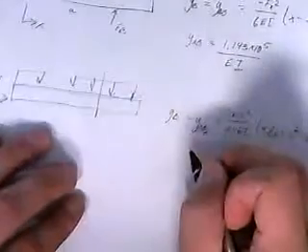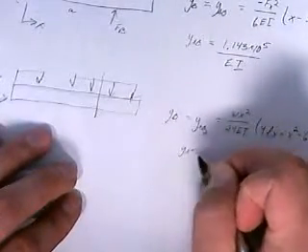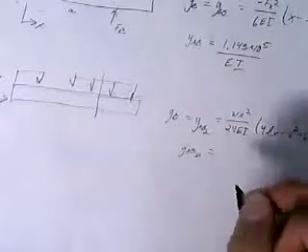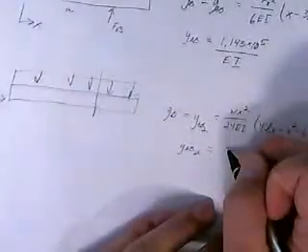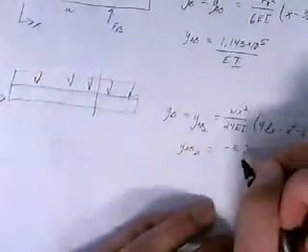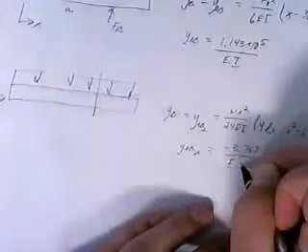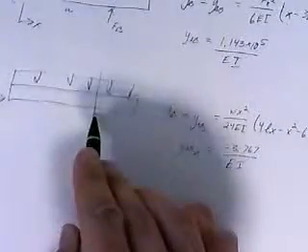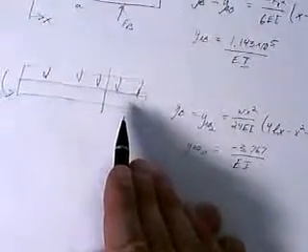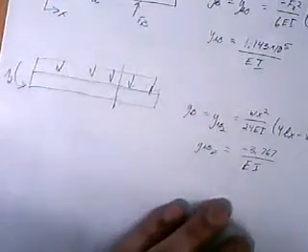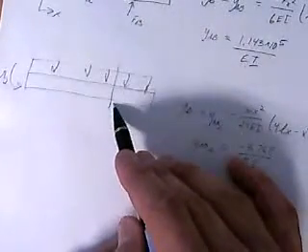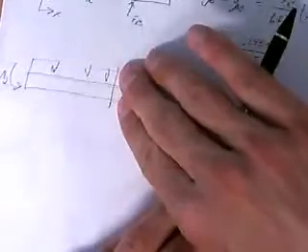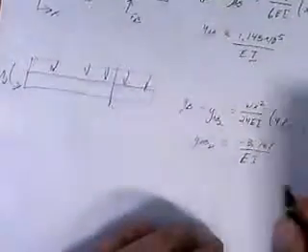And if you solve that all out, you'll end up with YAB2 is equal to negative 3.767 all over EI. L is the total distance of the bar, so 100. X is the distance to the point where we're splitting off, because we're basically ignoring this little chunk of ground. I'll just work it out for you. I'll show you the numbers here.